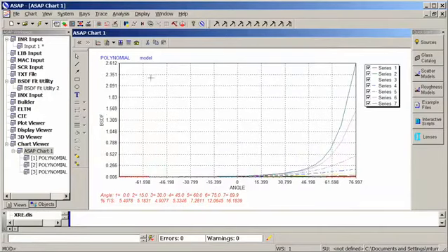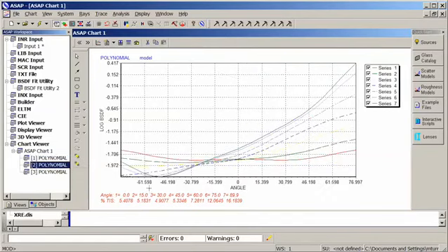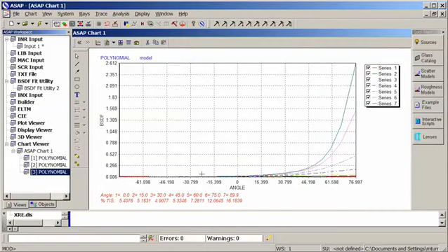scatter data looks like. And what we have is the log BSDF plotted against the log of beta minus beta naught, the sine of the angle minus the sine of the incident angle. And here's the log BSDF as a function of the angle of incidence, both forward and back scatter directions. And this data is very similar to what we had in our initial curves, so I'm happy with this result, and I would then be able to apply this model to any ASAP surface.